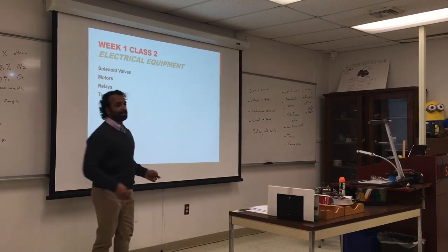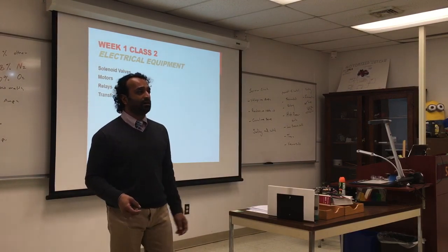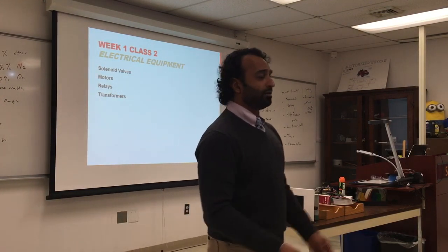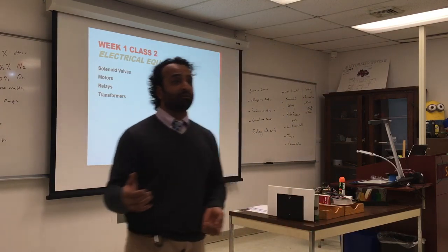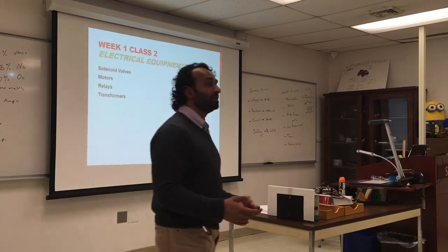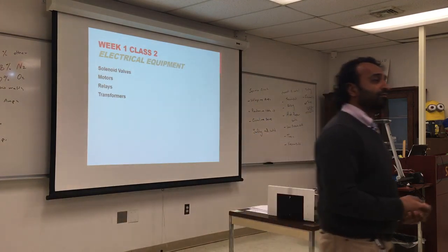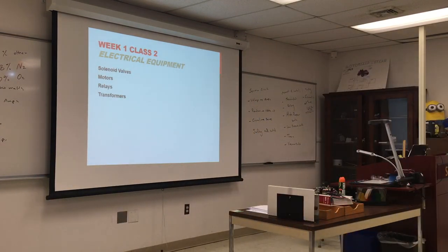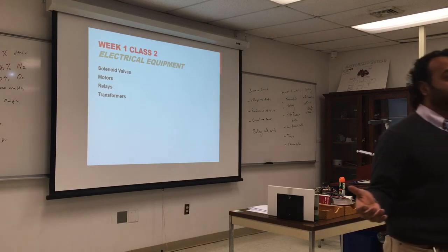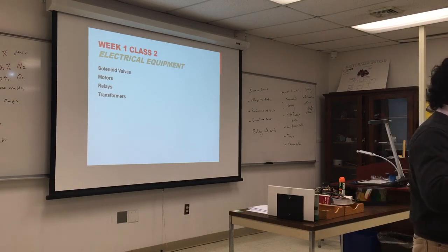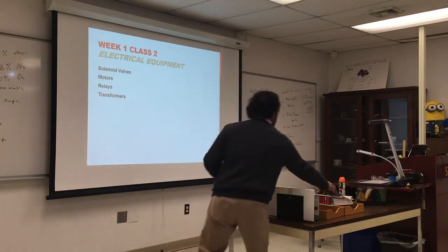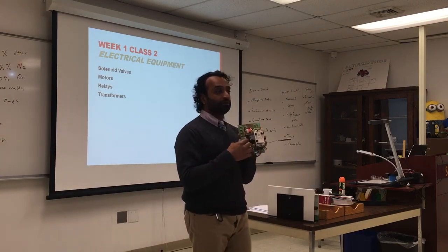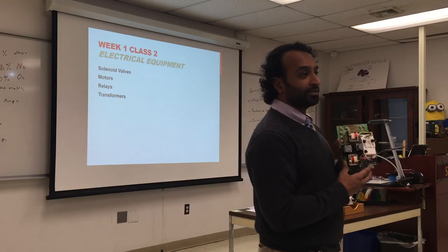We talked about relays, and we said relays are switches that turn on another circuit. So we have a circuit, and there's a sub-circuit, and sometimes other sub-circuits. Relays are the basis of us doing control and logic. If this light turns on, then turn off the other light. So one thing will go on, and something will go off. Relays control things.